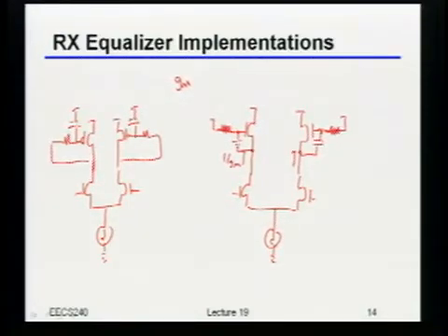Okay, well, what's going to say how much gm you need is really going to be the capacitance, and perhaps, therefore, the noise in your system. So you can very quickly run some back of the envelope. If I have this amount of noise, here's how much capacitive load I need to have, and therefore here's how much power I have to take. Ballpark numbers, you should be able to do this in the single milliamp range.